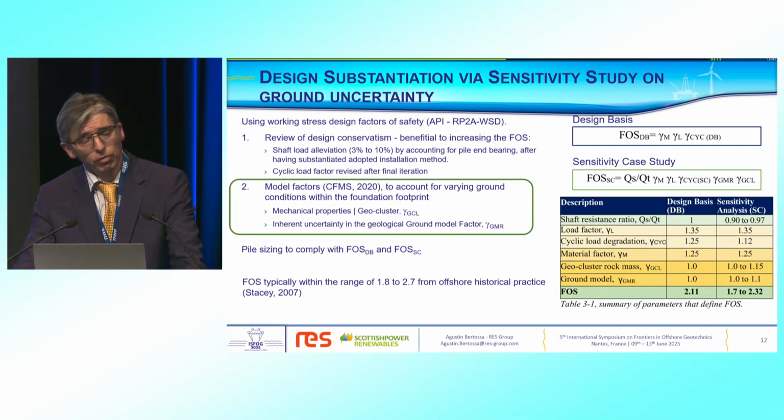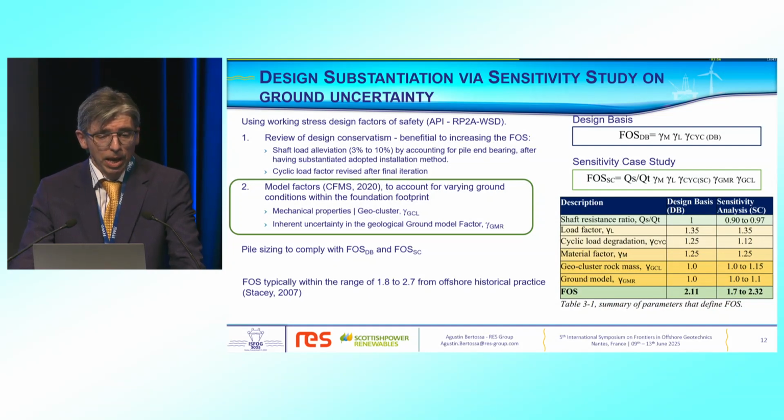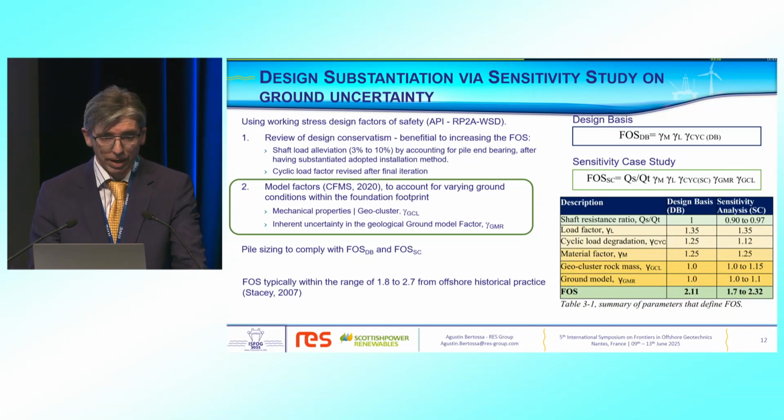And at the time, close to the installation phase, we took some improvements in the cyclic load factors and some minor consideration on the pile bearing, but equally we applied some model factors site-specific to each location to account for the variability or uncertainties in the ground model, and also to adjust the mechanical properties to be consistent across the global geological units.